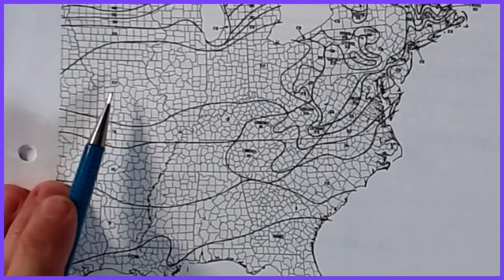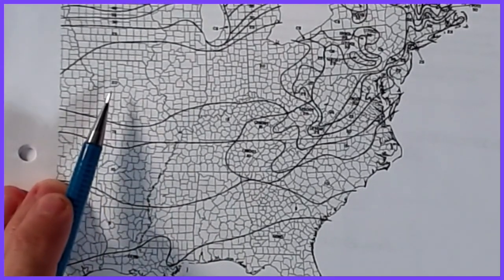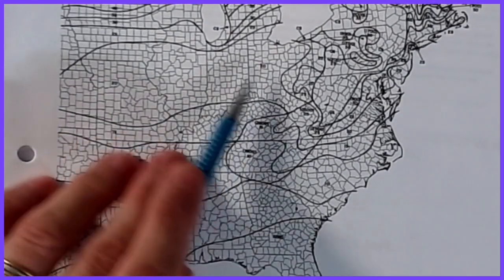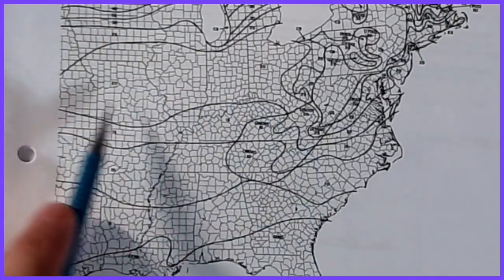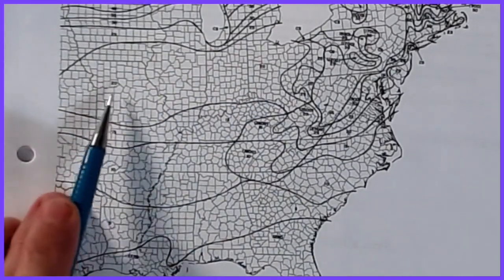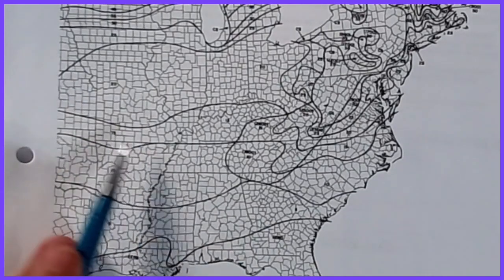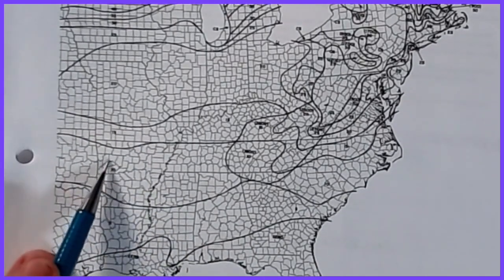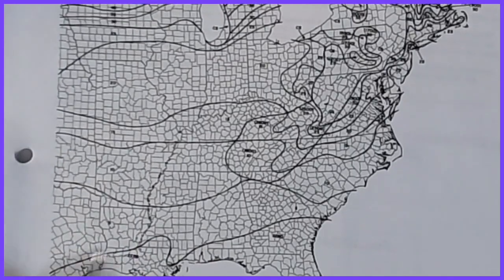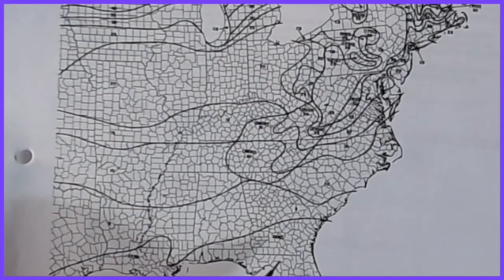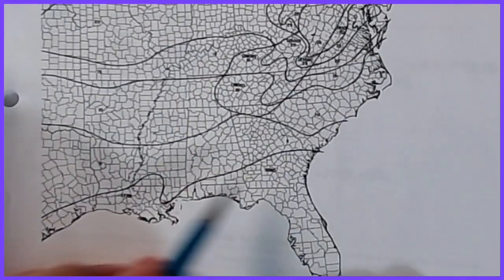Okay, and if you zoom in, and again, those of you that have access to this map in a print form or something, you'll see that through most of the Midwest, central U.S., we're looking at a ground snow load value of about 20 PSF. Then this band goes to 15, this one goes to 10, this one goes to 5, and then if you get down into here, it's basically a zero snow load value. They don't expect to get snow obviously down in Florida.